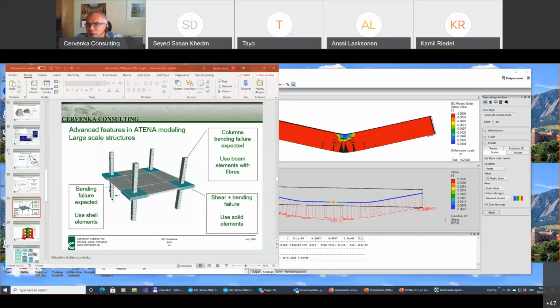Yep, that's okay. Then about the bond models, you mentioned crack spacing and tension stiffening. Basically, as I said, usually the bond failure in concrete is by cracking or crack development in the surrounding concrete. And this, of course, is very much dependent on the crack spacing as it evolves, and the consequence of this process of crack development around the reinforcement is the tension stiffening.